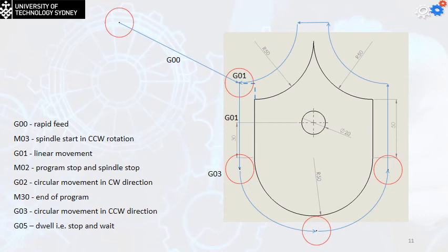the center point of the fourth cycle you can find here. So simply we are going to write down G03, x is equal to 105 in this case, and the y value will remain the same, but you have to write it down. So the y is going to be 45.